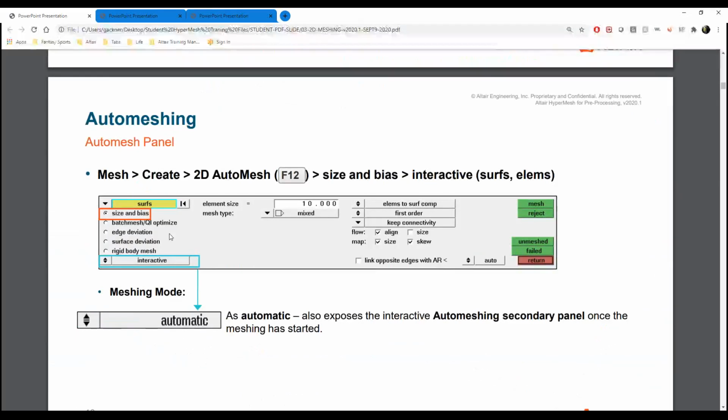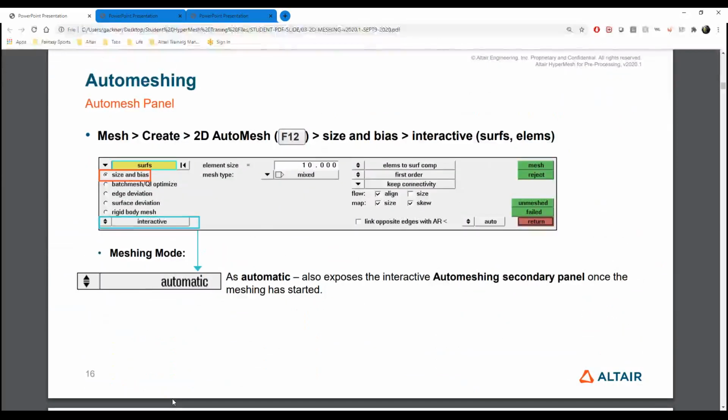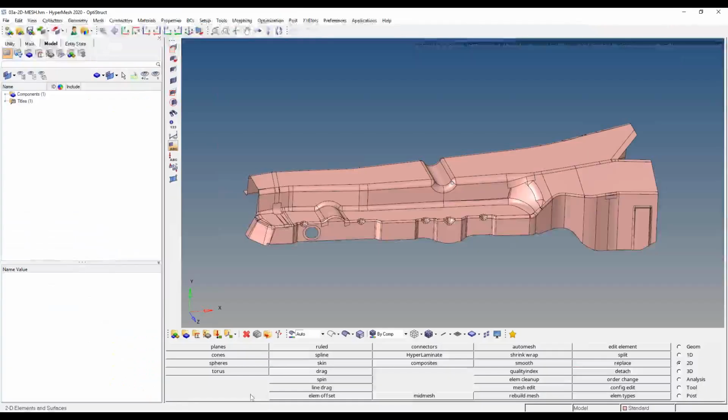So when I say that HyperMesh allows you to make adjustments to your mesh on the fly in real time, the most common way we'll adjust a mesh is by incrementing up or down, from 6 to 7 or 4 to 3 elements along a specific edge. I'm going to leave it here on slide 16 for a moment. We'll come right back to that.